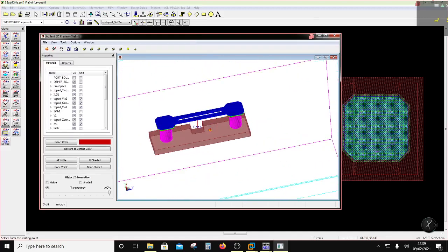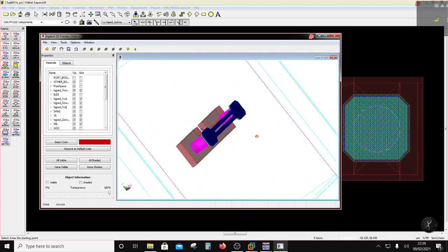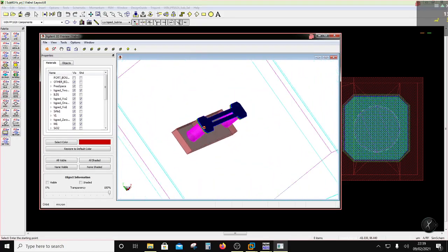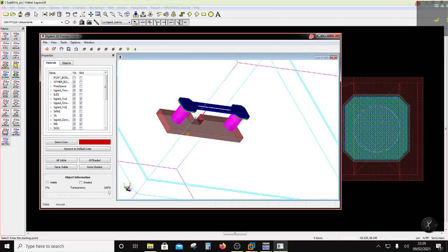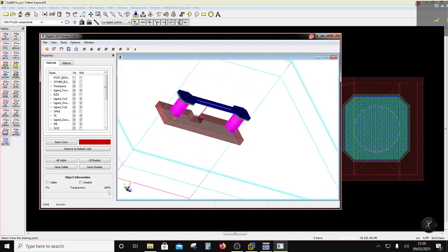Okay, so the device is sitting here, right? And then these substrate vias go all the way through back to the board, and this brown thing is the metal layer on the board, right? And these are the substrate vias, and the ground is established by these vias, which have an inductive ground.